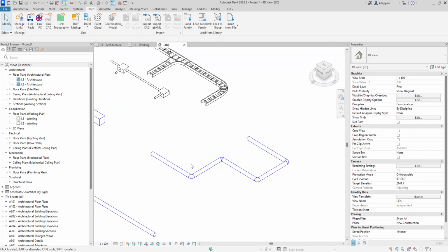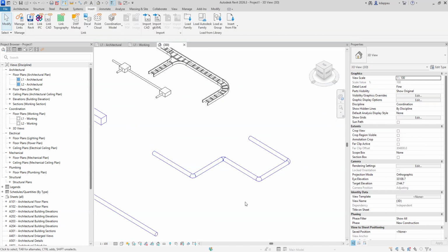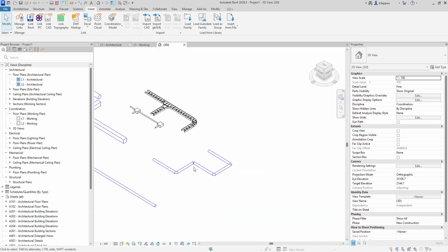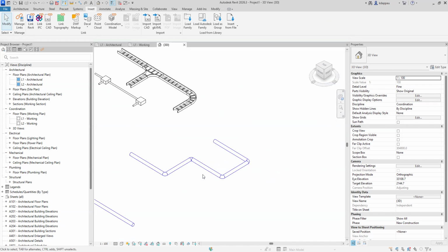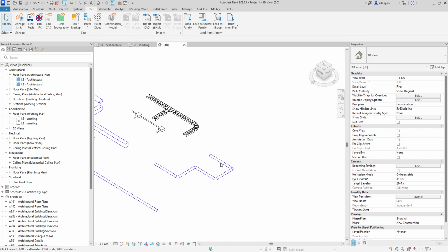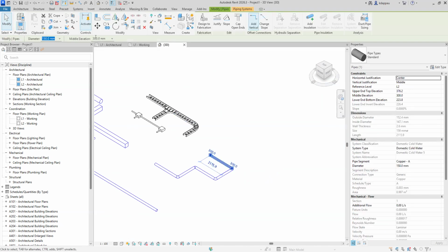But you do the settings for the fittings once. When the right settings for the fittings are done, I'm going to show you later on, but today we're only doing the introductory aspects. If the right fittings are assigned to the pipe, then you can draw it anyhow. Any pipe that you draw can have an elevation. Currently, this pipe that I just drew has an elevation of 300.